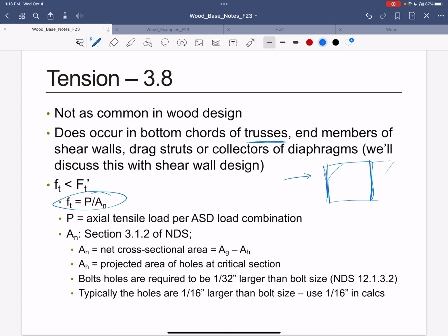So in pre-stress, it's that first term where we combine all those together. Sorry, I keep referring to pre-stress, but some of you had me in that class, and obviously I teach that one more than this one. But basically, this is just your pure tension or pure compression as P over A. Otherwise, it's going to be the same basic process. You have to remember, if I have holes or something else that reduces the cross-sectional area, I can only use the net or the part that doesn't have the hole, right?